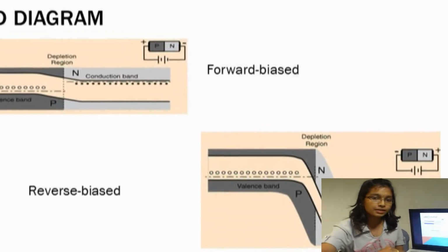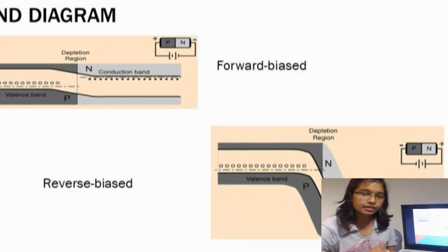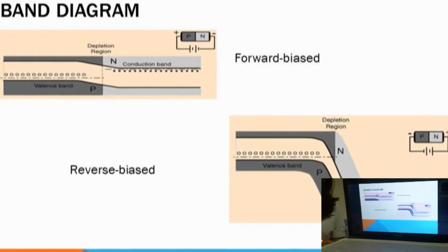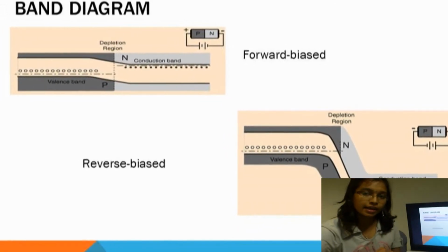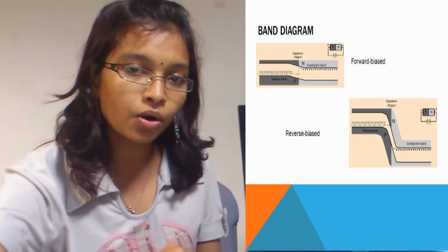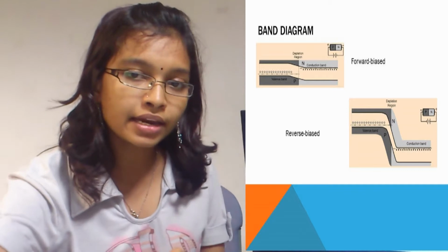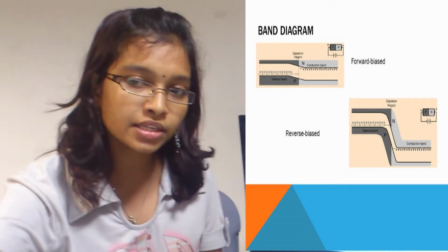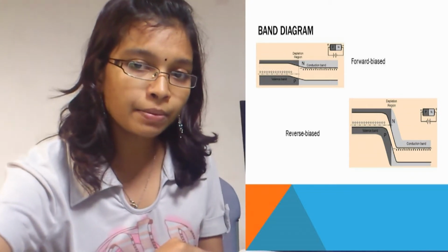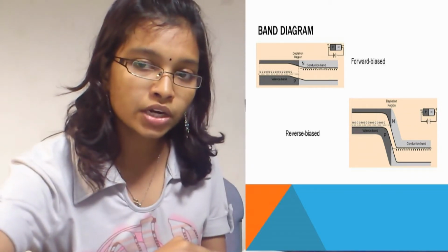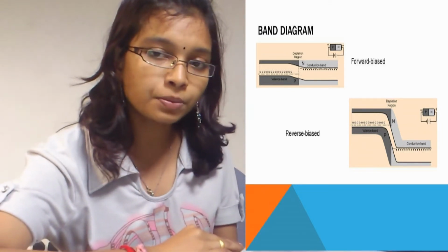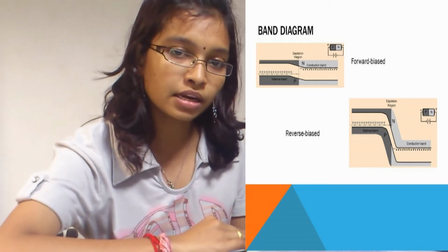To forward bias the PN junction, the P side is made more positive so that it is downhill for electron motion across the junction. An electron can move across the junction and fill a vacancy or hole near the junction. It can then move from vacancy to vacancy leftward toward the positive terminal, which could be described as the hole moving right. The conduction direction for electrons in the diagram is right to left, and the upward direction represents increasing electron energy.